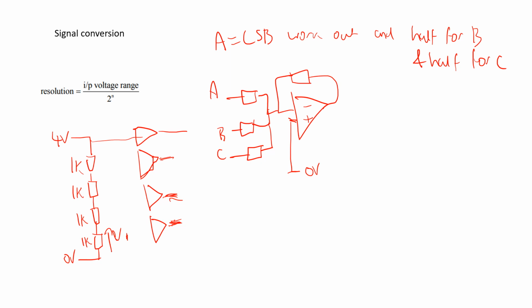This one is called a flash converter. They could also ask you, why would you use the SAR? Well, you'd use an SAR when time or speed is not an issue. Things like measuring the temperature of a greenhouse, you don't need it to convert straight away. But if you're measuring something like audio, which needs to change rapidly, then you'd need to use a flash converter.